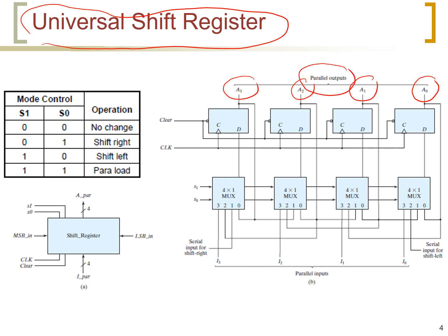And each flip-flop will have a D input and a clock input, and all the clock inputs are connected to one common clock, which is always the case. And also, all the flip-flops are connected with one common clear input, as we can see here, and this is active low, which means when clear is 0, the register will be cleared. Sometimes we call it clear bar if we want.